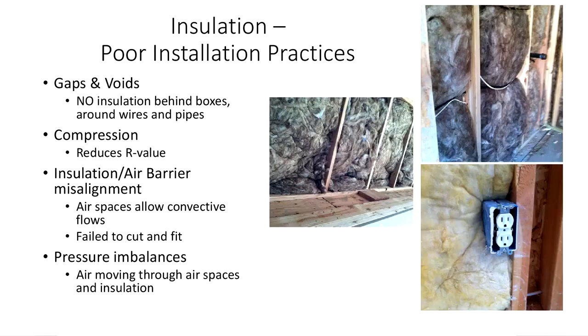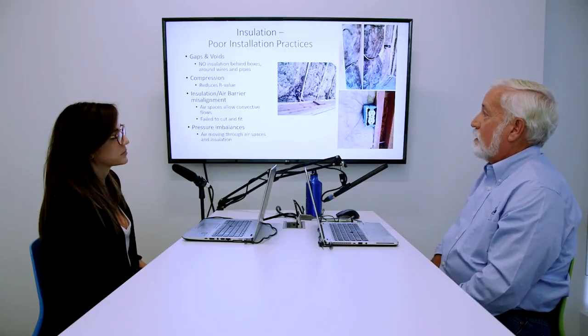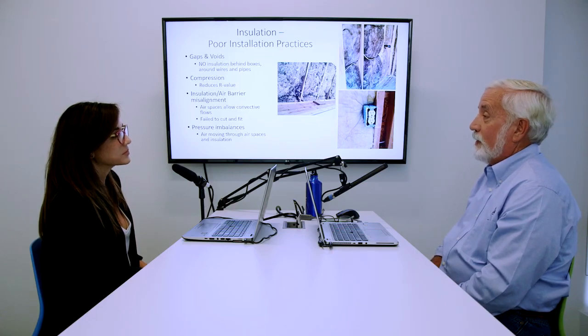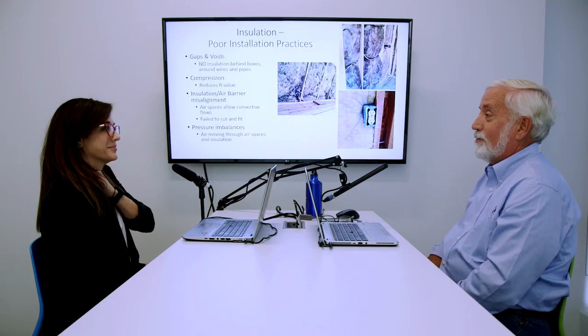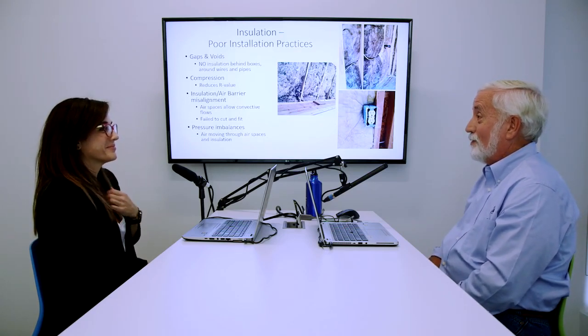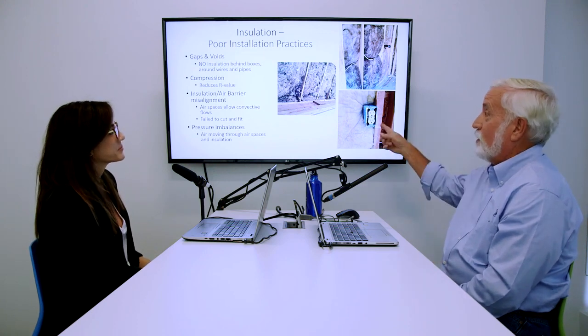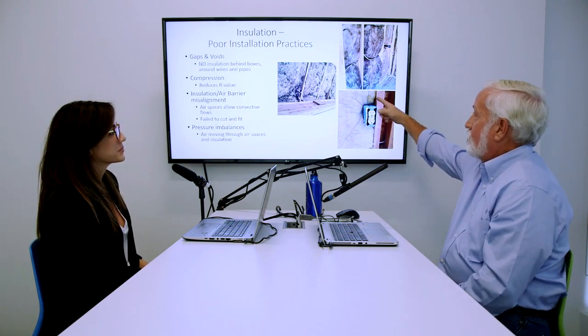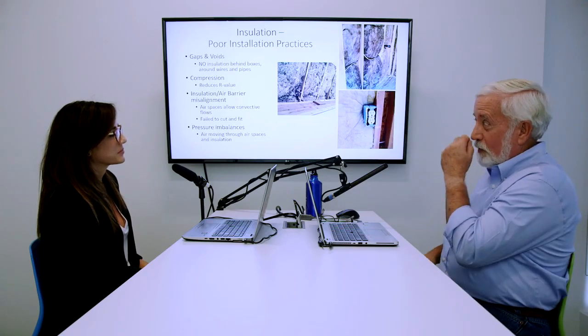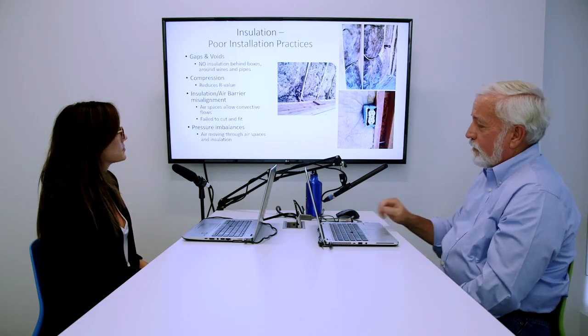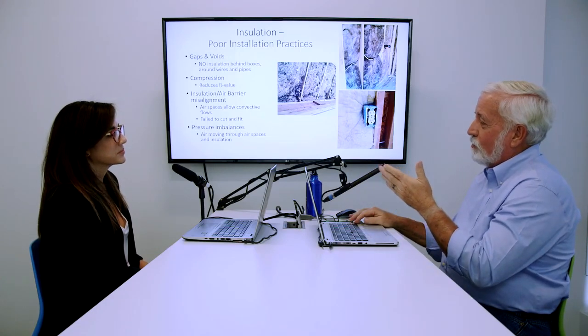And you know what? I'm not going to blame it all on the installation people. I remember it's probably my first year I was doing inspections. I went on an inspection, and it was really bad, the insulation, and I failed the insulation. And the builder called me just freaked out. No one fails insulation inspections. And I says, well, that's because no one's requiring you to do it right, because none of the boxes were done correctly. Instead of doing this, it just came out and wrapped around, and so you had a gap here and a gap here, and it was just really poorly insulated. If we understand the building science, we know that we need to do better.